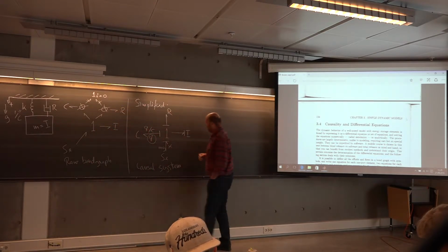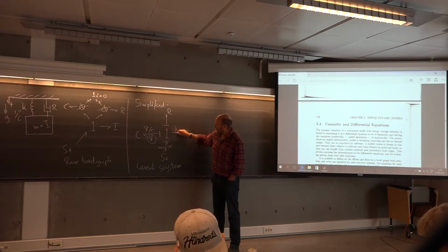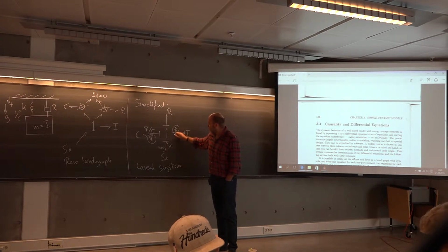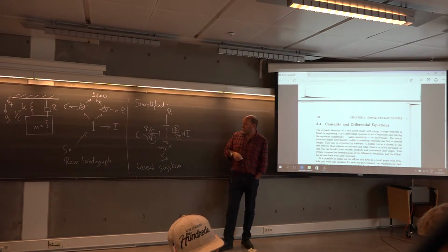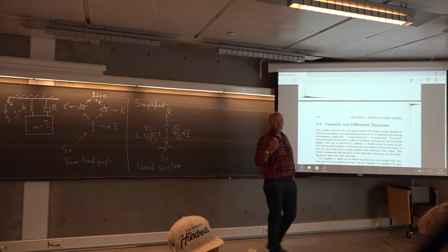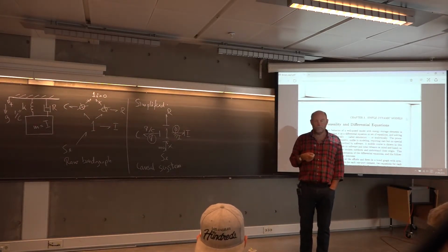the time integral of q, divided by C. While for the inertance, you will have the effort called a p dot, and also here with a circle around it, and beneath as the flow, p over I. So the circle now indicates a differential equation. So now we can tell immediately this is a second order system.